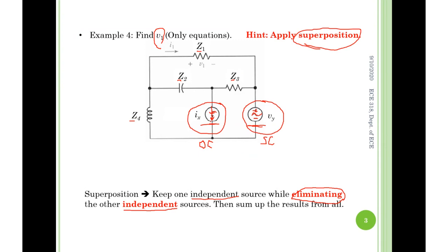So keep this concept very solid. Okay, open circuit, you can only know the current is guaranteed to be 0. What's the voltage? No, you don't know. Don't even guess. It all depends on the rest of the circuit. Similarly, what's the current through the short circuit here? Same thing, unknown. Absolutely not necessarily infinity. It all depends on the rest of the circuit.